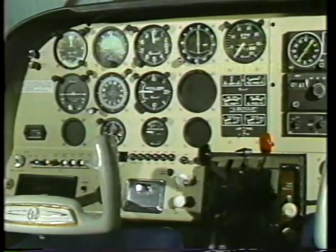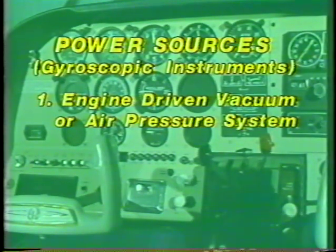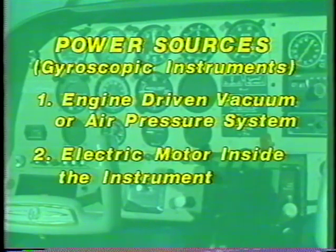There are two commonly used power sources for gyroscopic instruments. The engine-driven vacuum or air pressure system is used because it is a simple, reliable system and is usually the power source for two of the three gyro instruments. The third gyro is usually powered by a small electric motor inside the instrument.